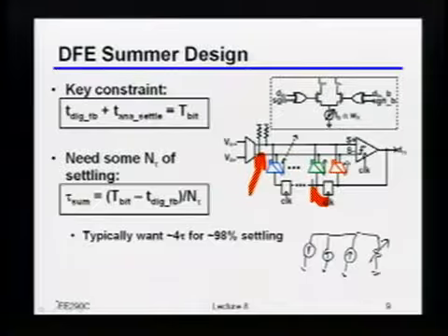So that nonlinearity is worse than the GM of your preamplifier? It depends. It's not necessarily worse, because it really strongly depends on what the RO of those switches is, and what the V star of those is compared to the V star of the input device. Exactly how big that nonlinearity is really strongly depends on the exact design you're doing. In practice, you can actually do a very large number of taps and not necessarily have it be too big of a problem, as long as it doesn't cause you to compress too heavily.